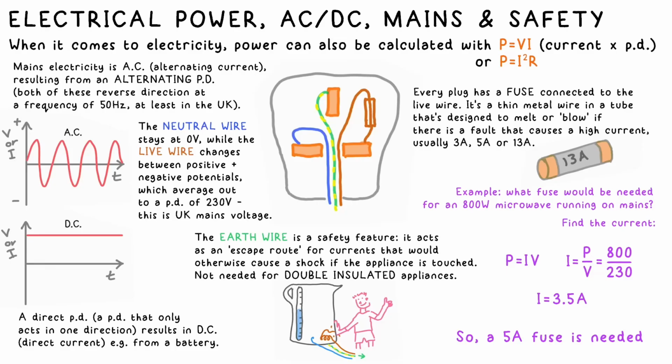We can't use a 3 amp fuse, otherwise it would just blow under normal operation. So we go for the next one up, a 5 amp fuse. A 13 amp fuse would work as well, but the current would have to increase to that before it blows, and that could be more dangerous.